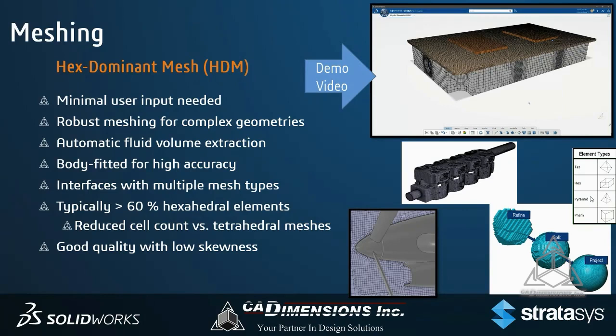We can just go ahead and sweep a mesh right through that versus having to create either a Cartesian mesh, a tetrahedral mesh. However we want to build that mesh, we can just go ahead and say, okay, I'm going to sweep the mesh through with 5 layers or 6 layers, whatever we think is necessary to capture those physics, and go from there. It's much, much easier to solve when our elements line up correctly like that.